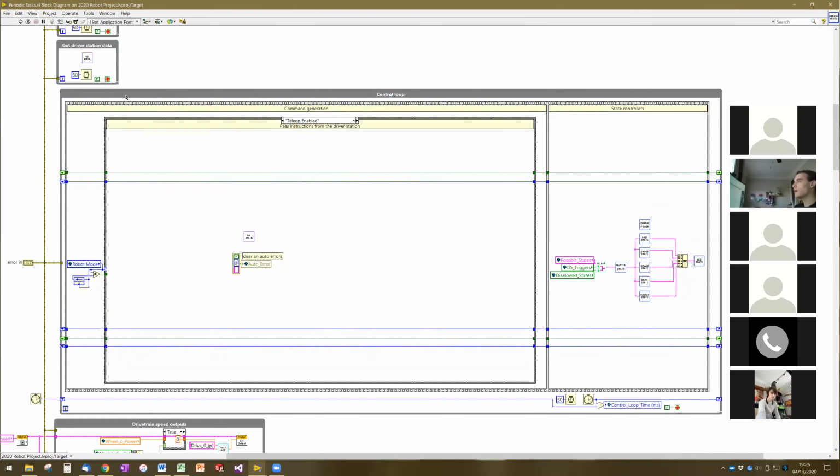So we have one master control loop that is running in periodic tasks that is handling all of the decision making for the robot. Some teams like Mars run separate control loops, so each subsystem will run in parallel. Their shooter, control panel spinner, or their climber will all have separate control loops. There are some advantages to that, but I think that overall there's more disadvantages.